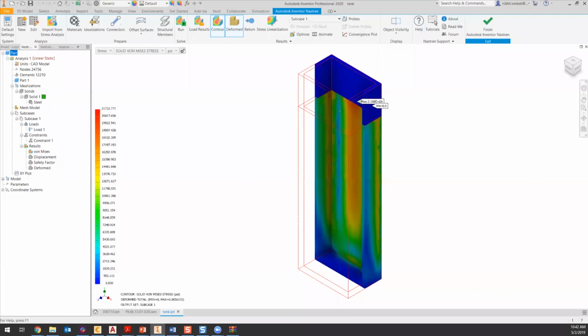Why did I use two bodies instead of just adding a split line? I didn't add a split line. I believe I split the body by mistake. So that's why we have two bodies now. Yeah, if you just add a simple contact here, that should fix the issue.